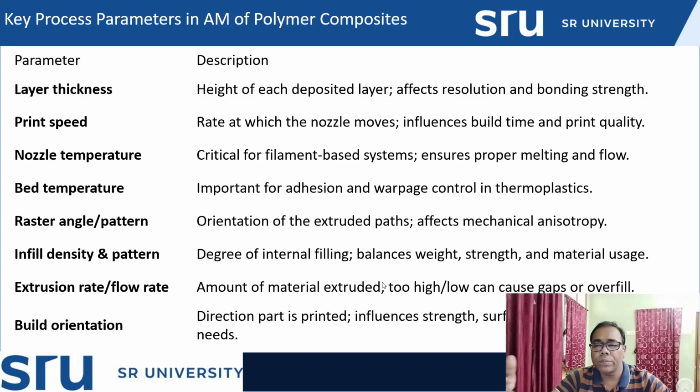So uniform melting, partial melting of the material will not be taking place evenly. That may lead to some other defects. In that way it will decrease the print quality and the strength of the material. Similarly, another parameter is the nozzle temperature.